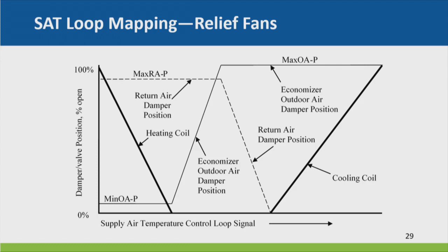And then on top of that is the economizer controls. So we have these variables, max OAP and max RAP, and these are numbers that are a function of the economizer. Right now it's showing the economizer as being wide open. There's another logic that turns it off, right? That says, oh, it's not good for economizing anymore, and it'll make max OAP equal to min OAP if it's controlling minimum outside air. And the same with the return air damper logic.